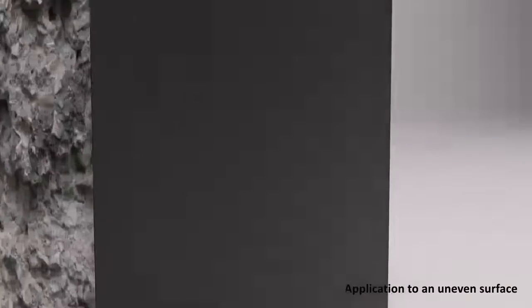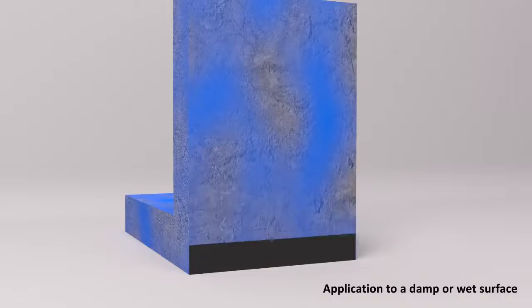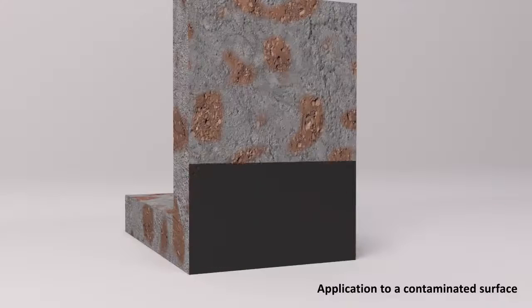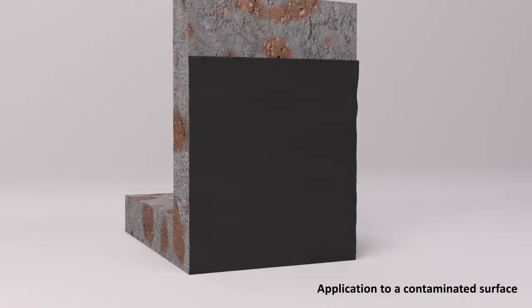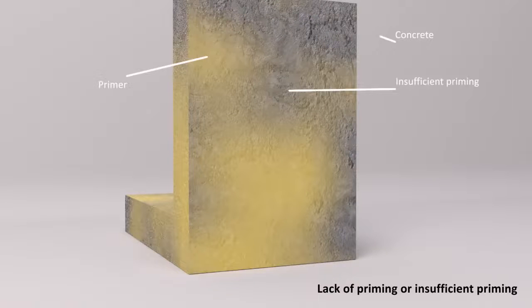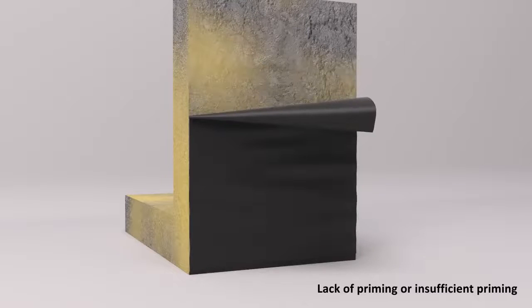Debonding can be caused by a number of factors, including application to an uneven surface, application to a damp or wet surface, application to a contaminated surface. Lack of priming or insufficient priming of the surface prior to installation of the waterproofing membrane can lead to debonding.